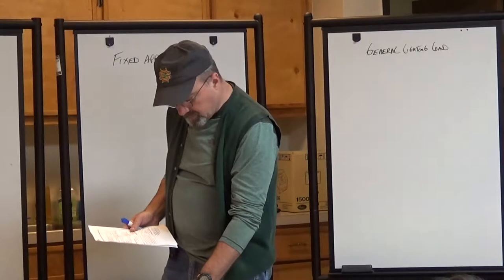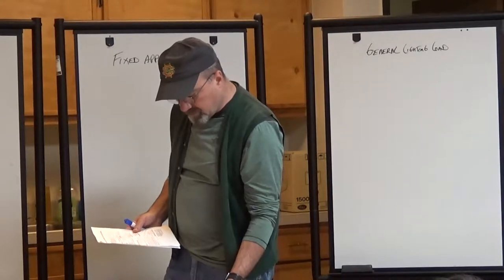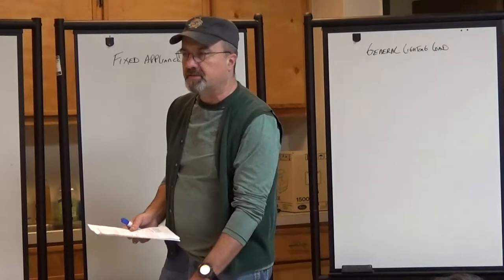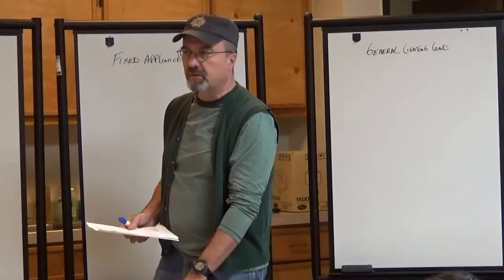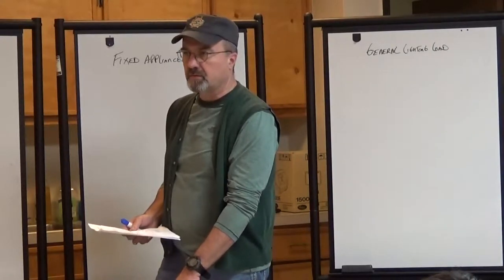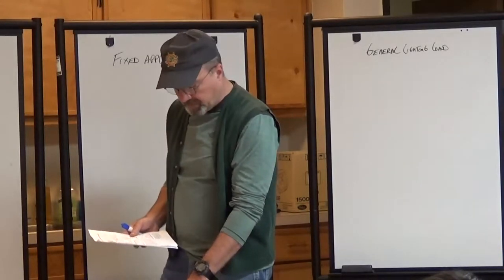For dwelling units, the calculated floor area shall not include open porches, garages, or unused or unfinished spaces not adaptable for future use. So there's a couple of points there. When we are looking at the square footage area of the dwelling unit, we do not want to include the carports, porches, those areas.